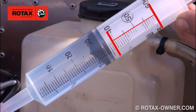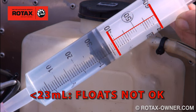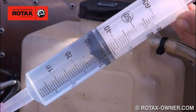If the amount is less than 23 milliliters, there is a significant deviation of the float levels. A detailed inspection of the floats and a check of their weights will be necessary.